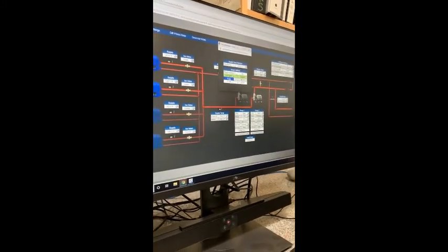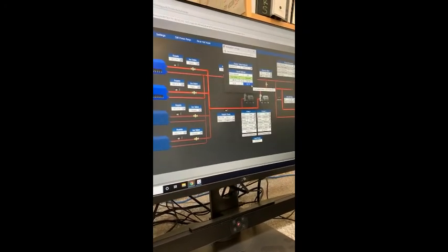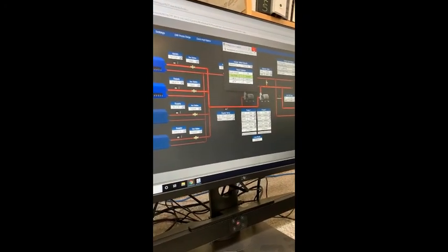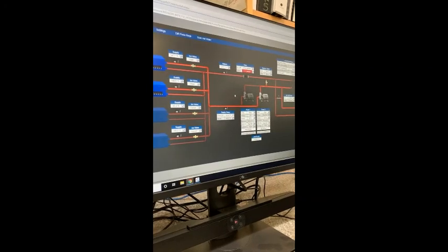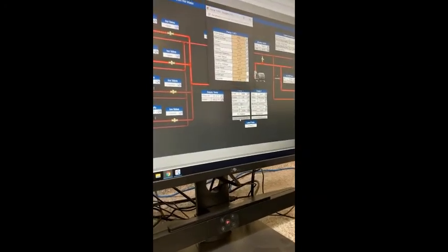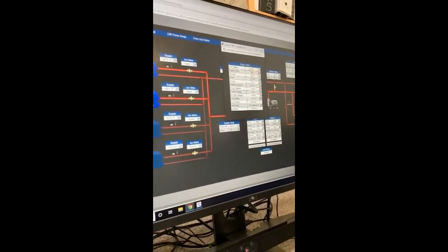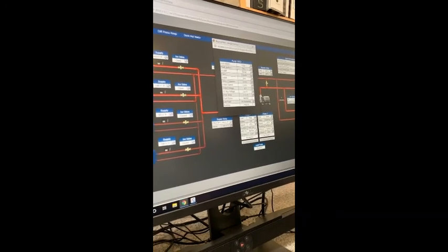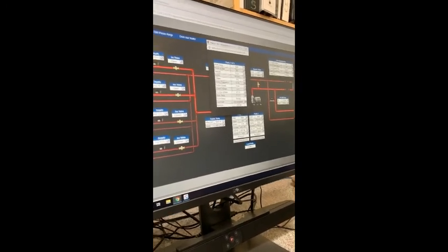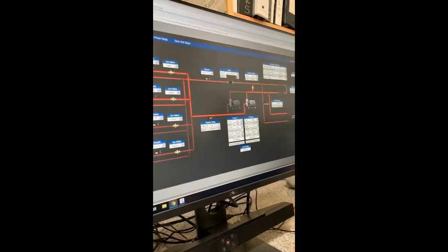Where the outside air temp is 55 to 60, it'll send 130. Pumps work the same way. Yeah, each pump you can actually click to get more info from the drive. And same with, I forgot to go over this with the chilled water, but from here you can see if it's already the drive. Actually, let me take a look.